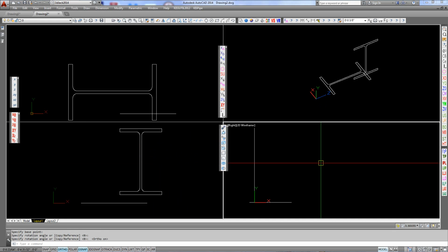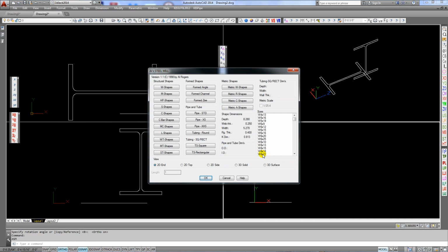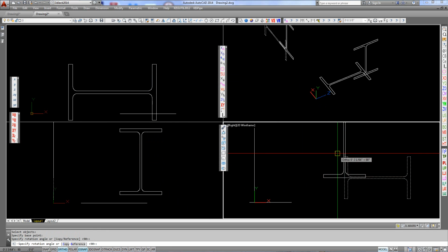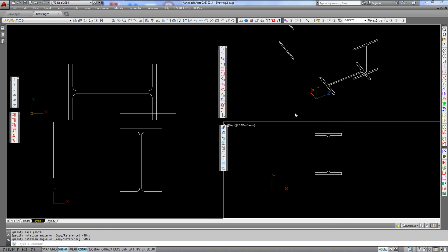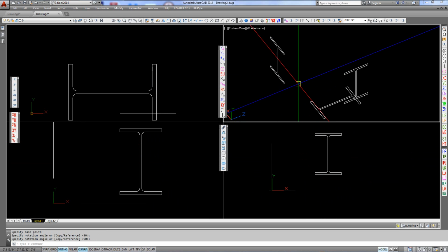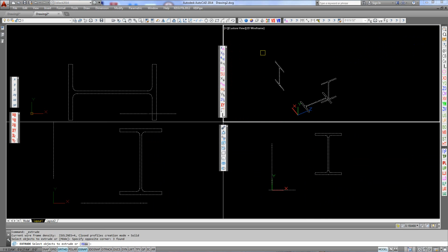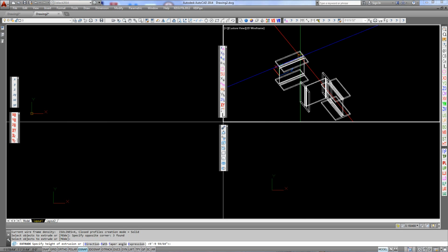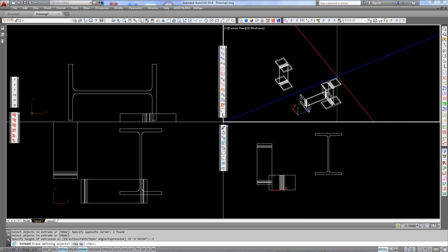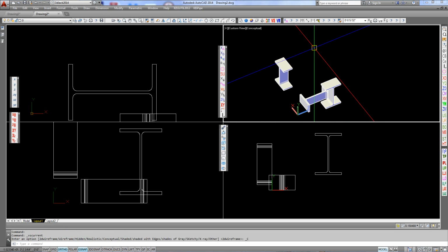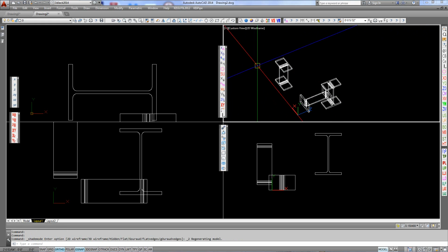If I go to the right hand viewport and repeat the same thing, inserting the same piece of steel here and dragging up, you see we have it in three different orientations. So depending on which viewport you use is how it'll be oriented, and you won't have to do a bunch of extra rotations possibly. We do an extrude, we pick 3 inches. You can see each of them has been extruded so that you can tell where they're going and what they're doing. Alright.